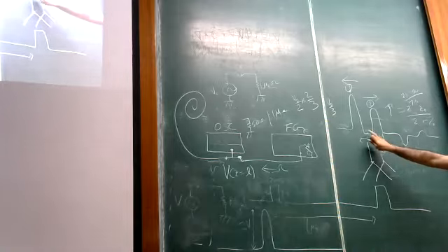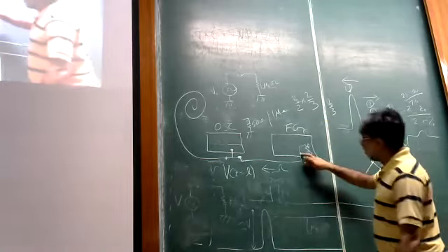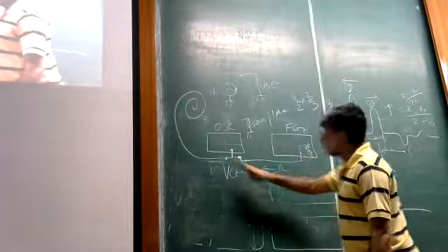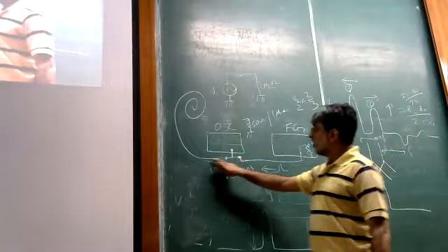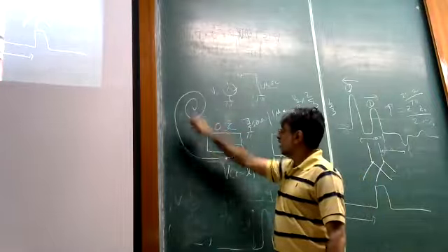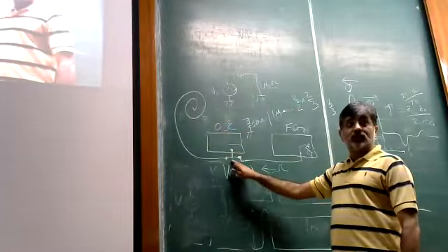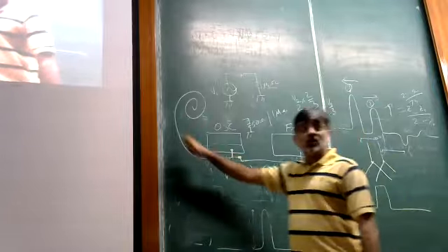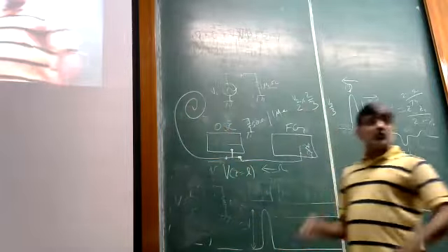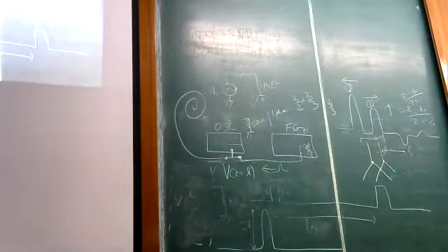So this is the first pulse which is going from the function generator to here. The second pulse is the transmitted wave going all the way to the cable end and coming back. The third pulse is the reflection of that pulse going all the way and coming back. So it's the same thing which is happening. It's just like you have one long cable and the pulse is going back and forth. So there's no instantaneous part here.